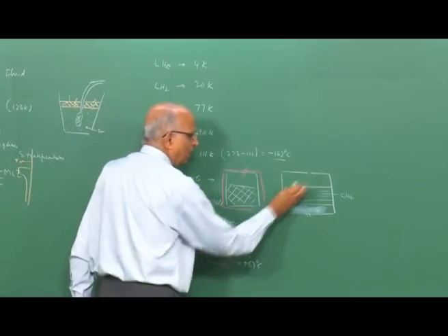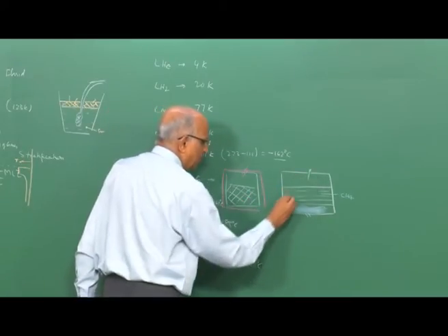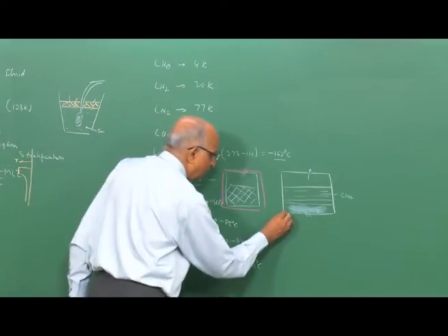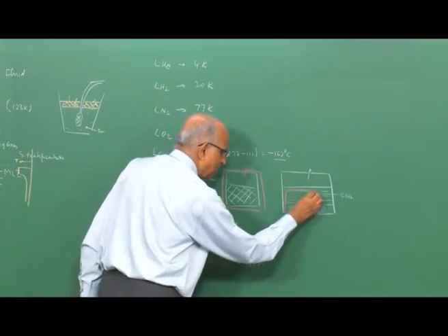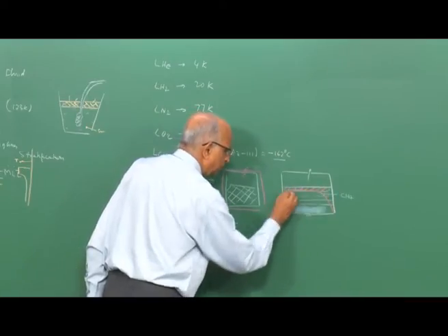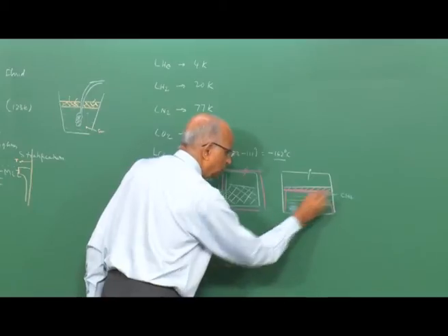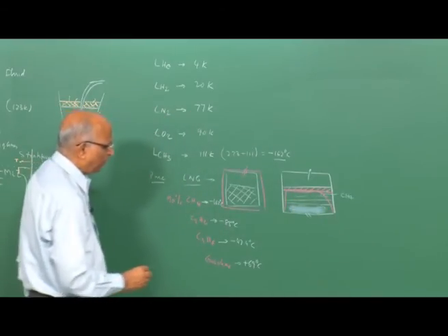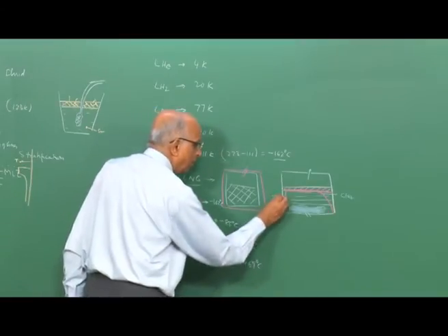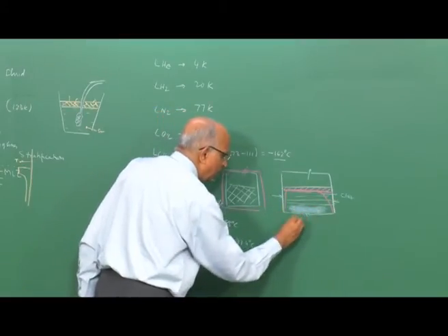Of course, you have a vent valve over here, and because we talked in terms of stratification, we said I have a stratified layer on top. This is my stratified layer on top. Now, what is going to happen? It is not that heat in-leak occurs only from the side walls, but heat in-leak will occur also from the bottom.